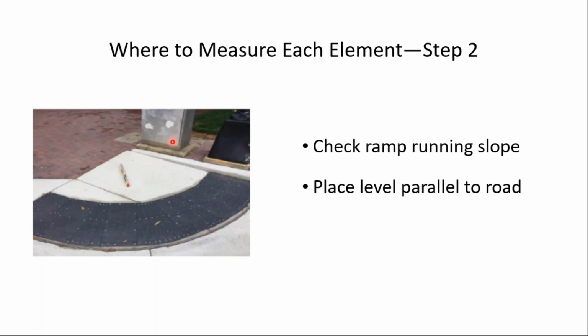But notice they prevent this area from being used as a pedestrian circulation path because of these obstacles. And so on this side of the blended transition, they have the vertical curb returns. And it looks like a flare over here. So you can do that. You just have to look at your specific situation in terms of, is it a pedestrian circulation path or not?